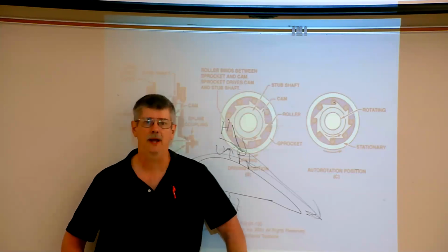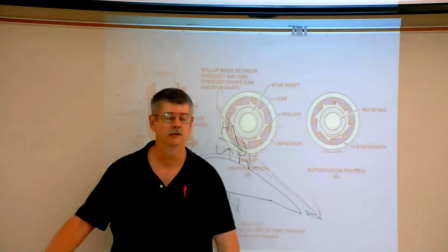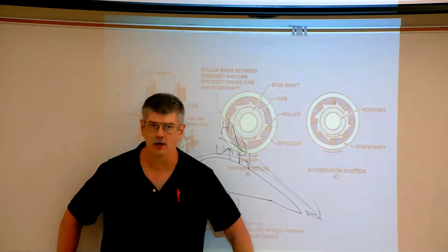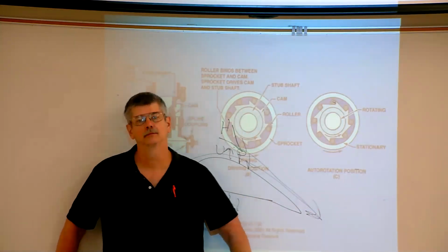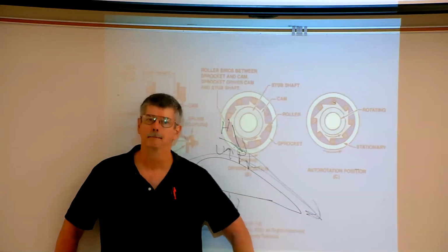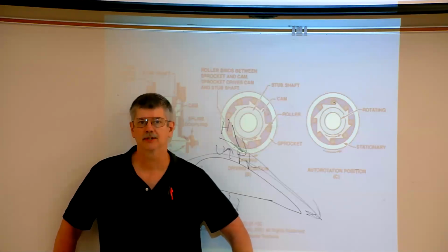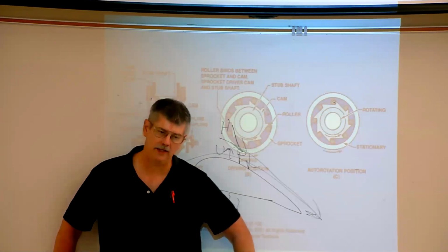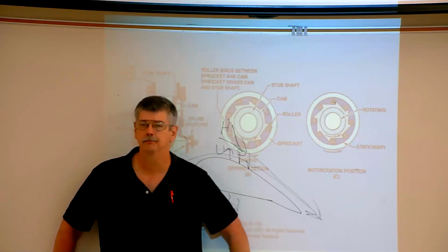Now, once the wing has been developed or built, we can't affect it anymore. So the pilot can control the lift by controlling the angle of attack. When we increase the angle of attack, the lift is increased. We decrease the angle of attack, we decrease the lift, okay?